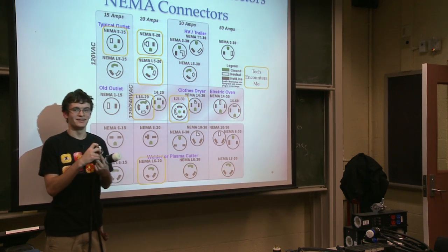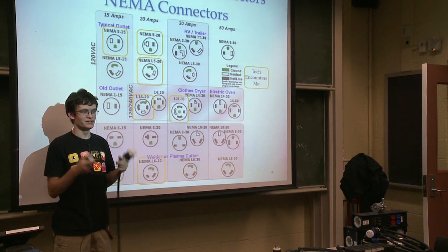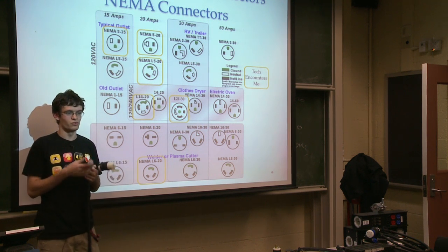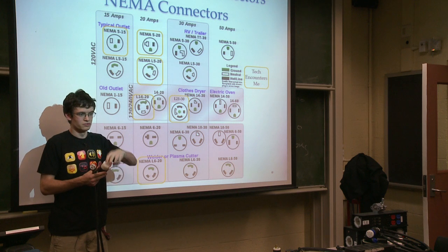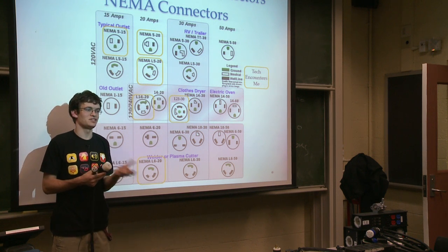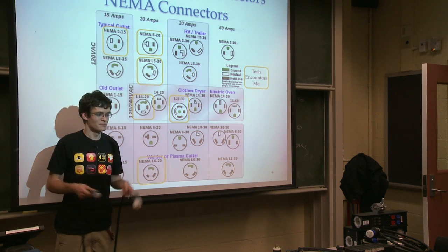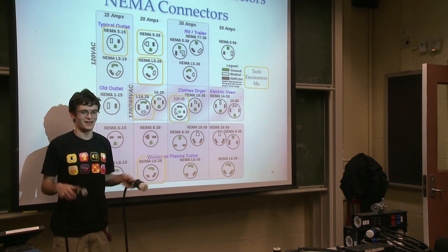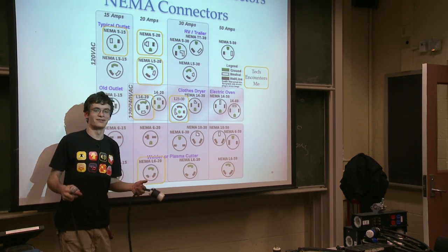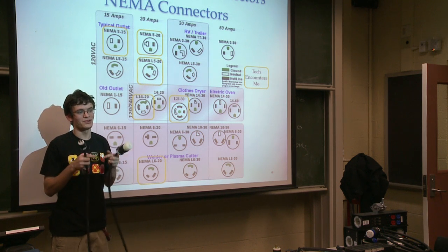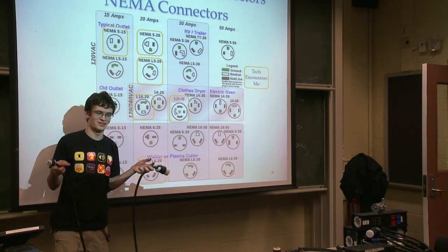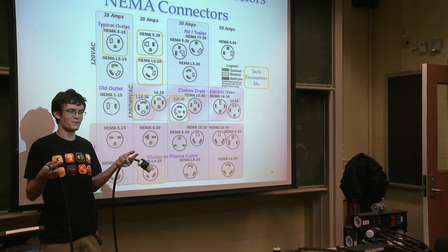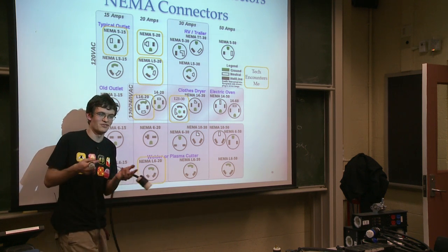Yes, and it gives slightly less power than you think. Because all the amps are 120 volt based, they just run off the different phases, so they each get enough power. So if you're only running one or two of the amps, at a low level and not near its capacity, this cable could actually let you use the amp tanks in places where they're not supposed to be used. This prevents you from having to rewire the amp tank every time you move it around.